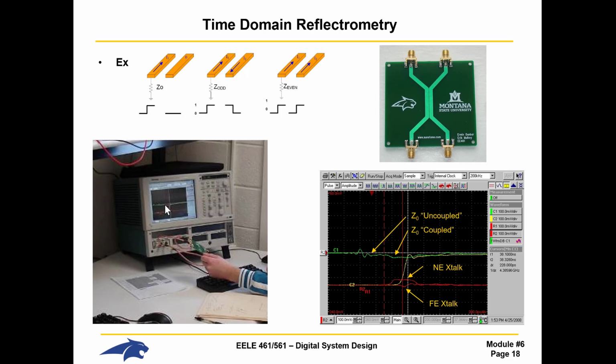But you can see it's an oscilloscope, and it's got the 50 ohm outputs. And what we're doing here is you see these nice thick cables. These are real expensive 50 ohm cables, so that they're exactly 50. They're not 45. They're not plus or minus 10%. They're rock on 50 ohms. And then you come into whatever DUT you're going to do. Look at this DUT right here.